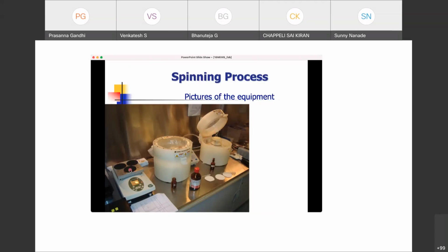After spin coating, it is given a pre-bake. Before it goes to the lithography machine, it is given a pre-bake in an oven or on a hot plate for some time. Once that is done, you take it to the machine and process it, and then after processing, you bring it back to the hot plate and do something called post-bake, or you develop and do the post-bake.